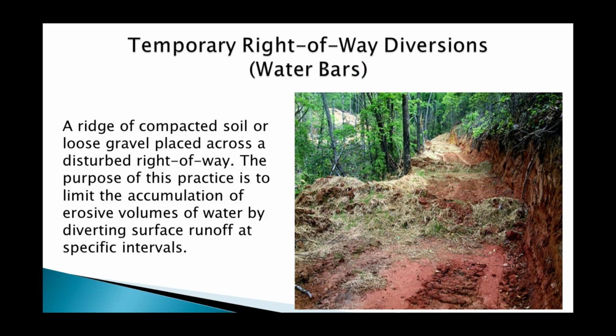The third device that's used on pipeline projects is temporary right-of-way diversions, otherwise known as water bars. A water bar is a ridge of compacted soil or loose gravel placed across the disturbed right-of-way. The purpose of this practice is to limit the accumulation of erosive volumes of water by diverting surface runoff at specific intervals. The primary purpose is to reduce the drainage area that's coming down into the diversions in